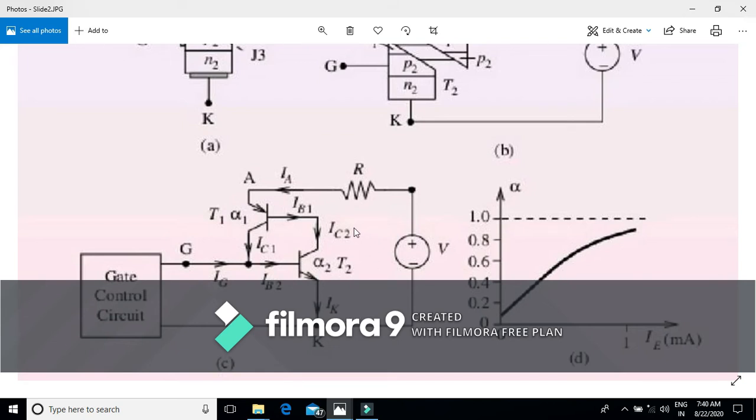This collector current is basically the base current for the transistor T1, and the emitter current for this transistor T1 will be the anode current IA. Since the anode current increases, the gain alpha 1 increases.